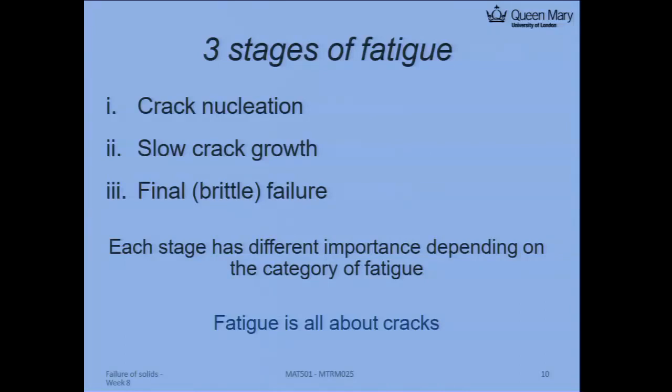So some voids eventually will connect to a crack and nucleate this crack. And once the crack has initiated, there's some slow crack growth region, and finally it will have a fast crack, which we normally call the brittle failure. And you cannot stop it. So each stage has a different importance depending on the category of fatigue. So fatigue basically is all about cracks.